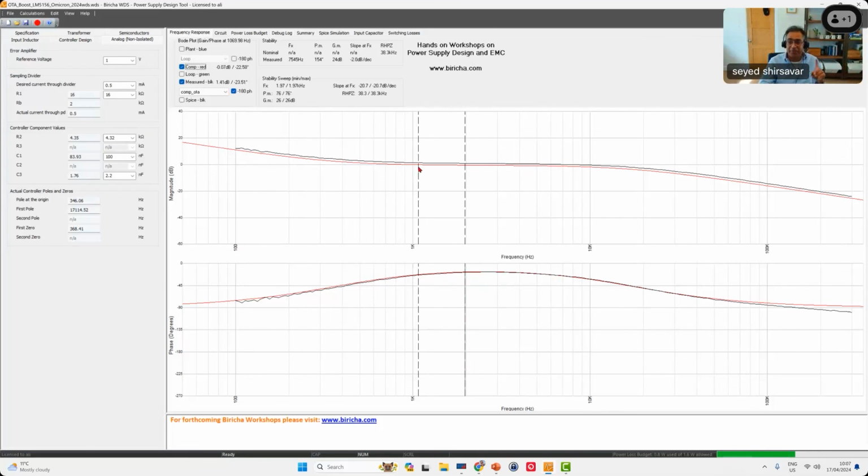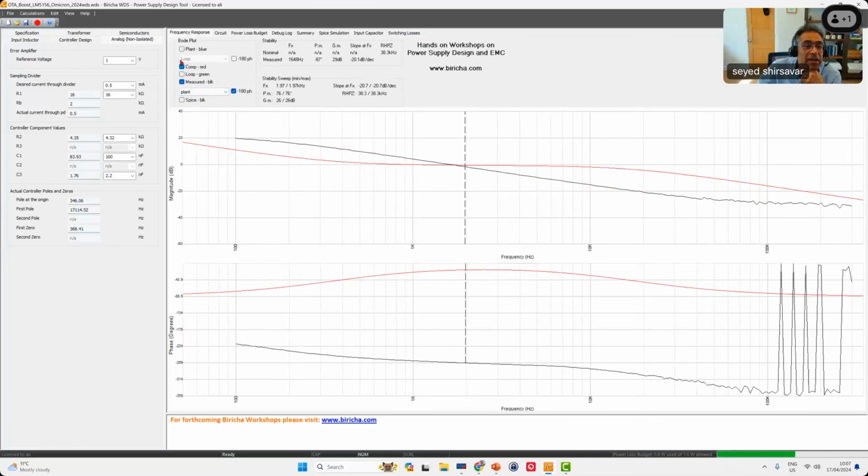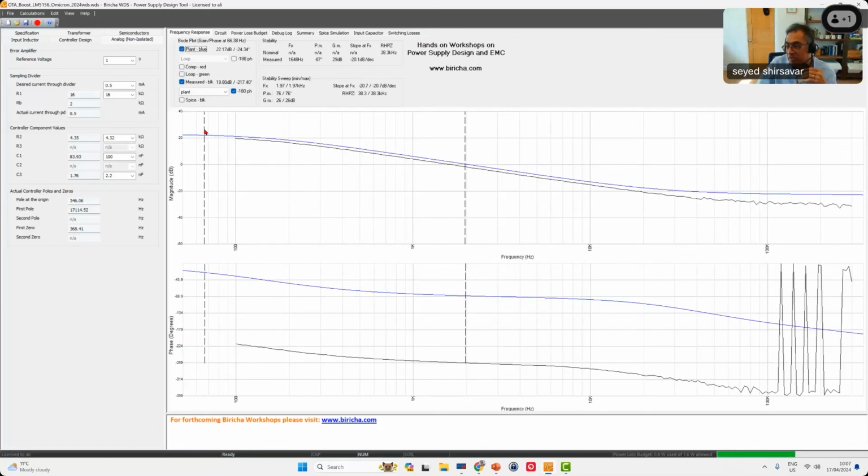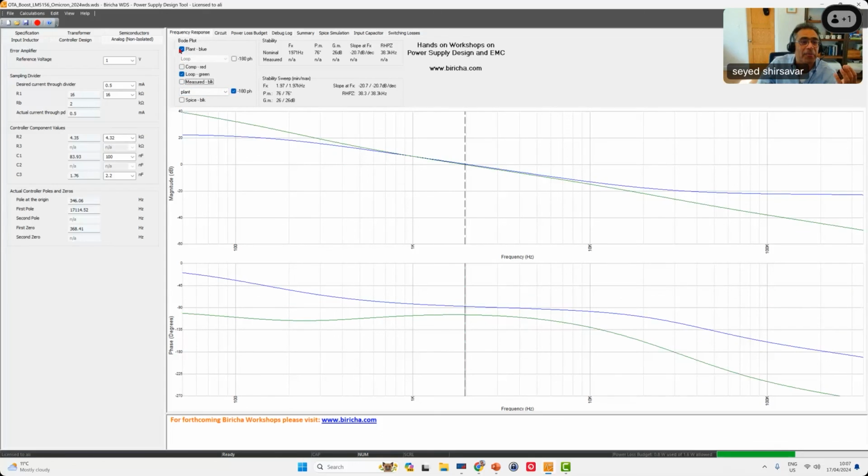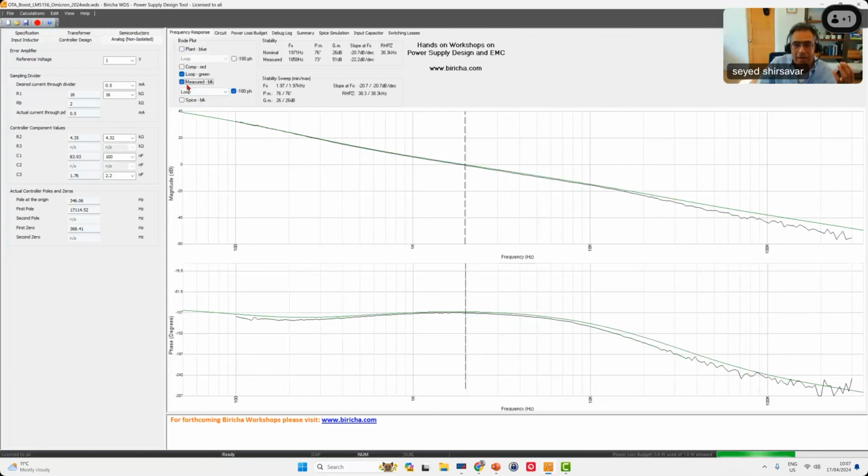The gain of the compensator is a little bit off. However, the gain of the plant is also a little bit off. Look at that. The gain of the plant is a little bit off in the opposite direction. So when I actually add the two together, I get a near perfect match, right? That doesn't happen all the time. One error is correcting the other error, right? So this is just pure luck. However, you can see that we have got a very, very close match.